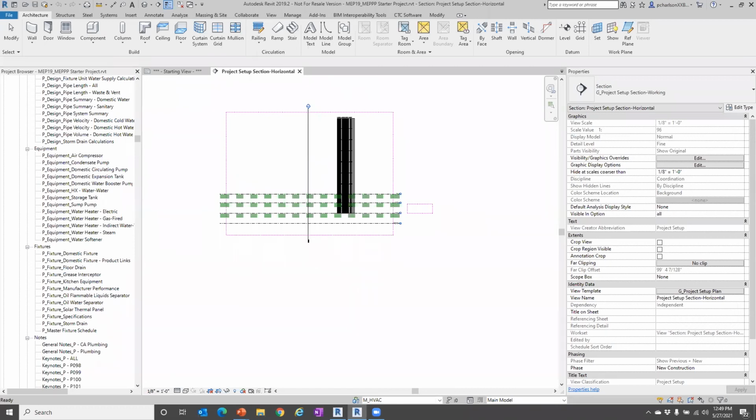So then obviously the reference planes show on all of the sheets that are in the project, and I can go in and place the views according to those reference planes. That's been the best way that I've been able to find, a way that you can do it right out of the box without any Dynamo scripts.